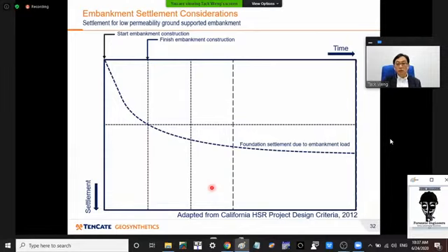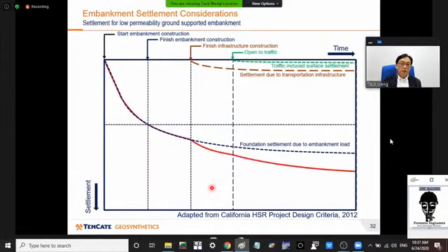The ground settlement caused by the embankment weight before the completion of the laydown of the pavement does not count, because what we are concerned with is that we don't want the pavement to have differential settlements, but what has happened before the pavement is constructed doesn't matter. So that allows us the trick of trying to force the embankment to consolidate as much as possible before we put on the transportation infrastructure.